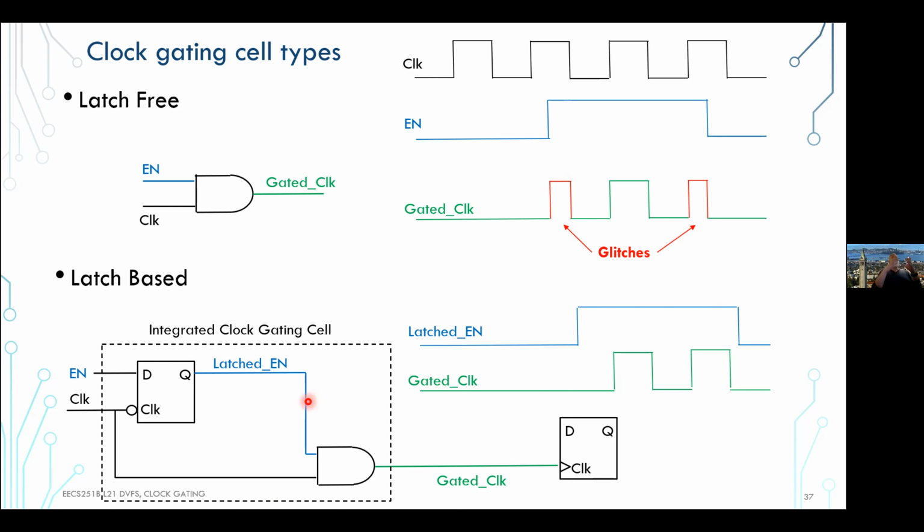People build essentially one single cell that contains both an AND and a negative latch, and then that cell is just inserted into the clock tree and very well characterized, so the tool understands what these little overheads in delay are that it needs to pay attention to, to not create glitches in the network.